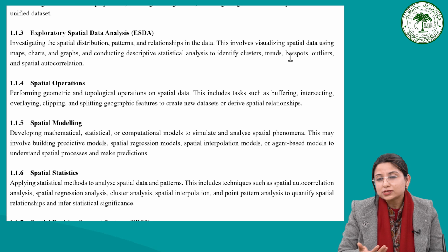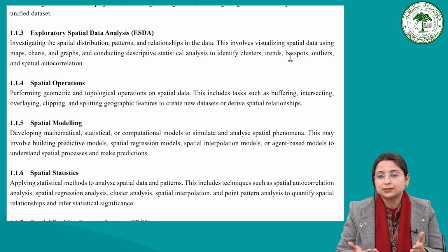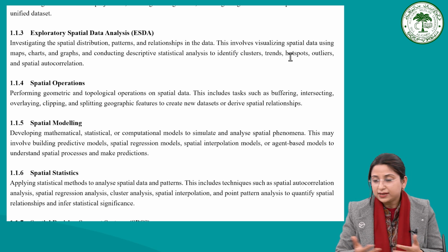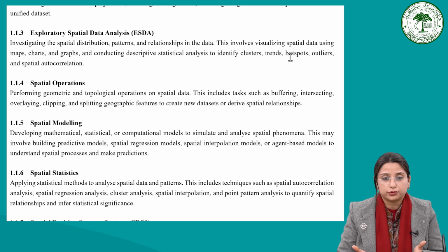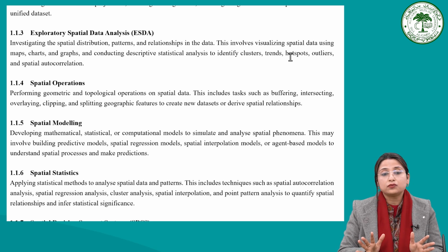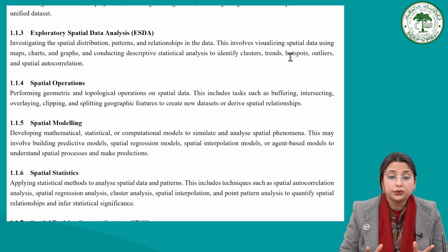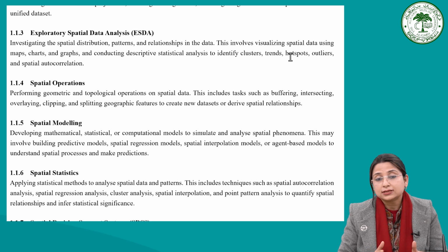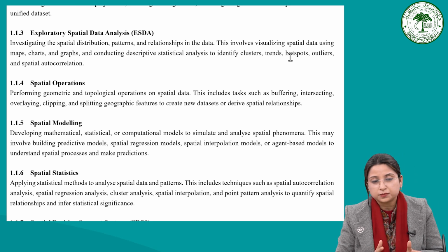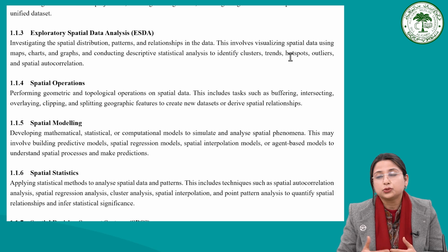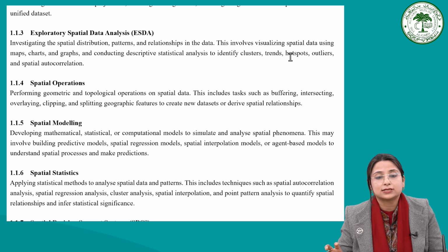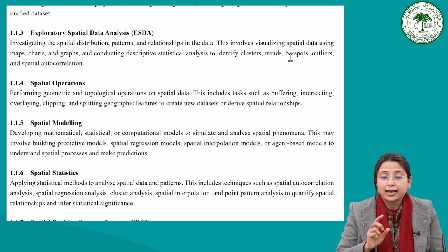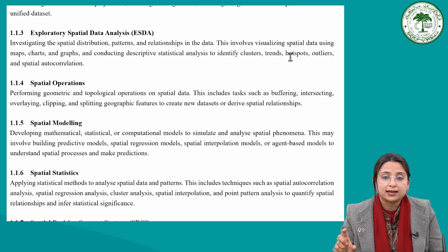So we investigate the data for certain clusters, trends, hotspots, and many times also investigate to find out certain types of spatial autocorrelation. In this, we are just visualizing, exploring, and finding out certain types of patterns, relationships, and clusters by using different types of maps, charts, and graphs. So that's why this component is known as exploratory spatial data analysis, that is ESDA.